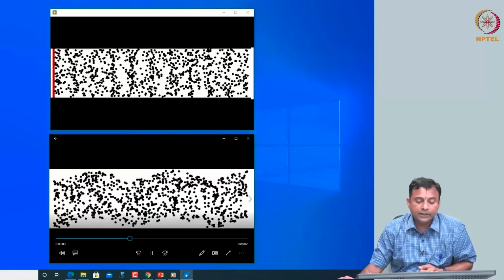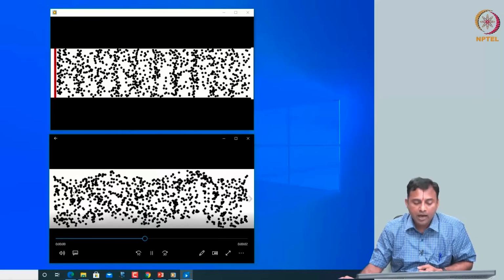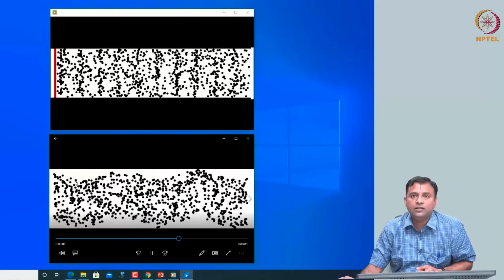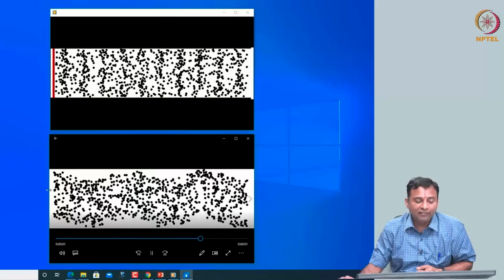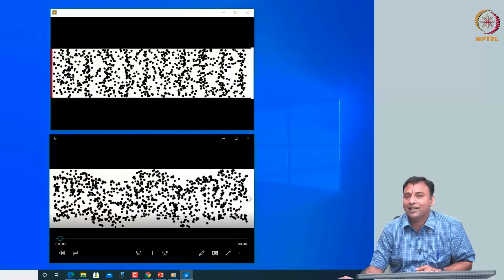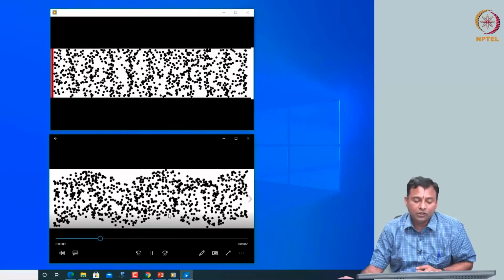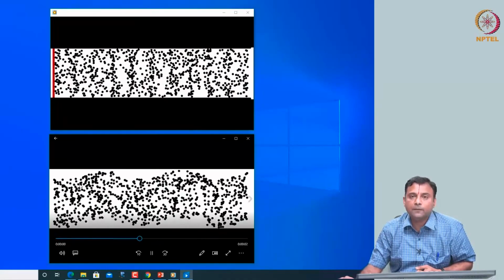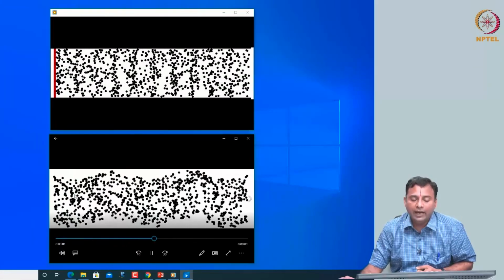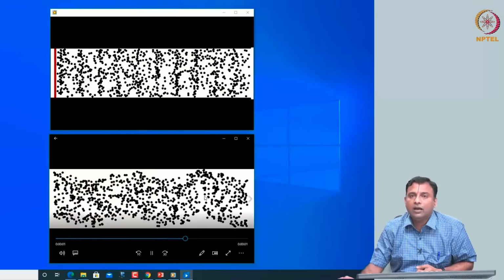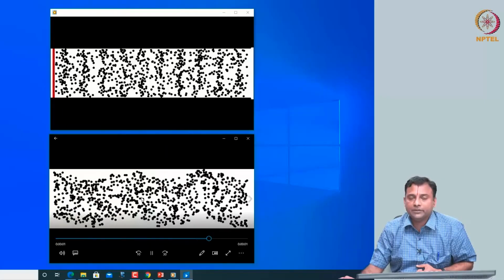So the particle is actually going up and down around its mean position, whereas the wave is going left to right, perpendicular to it. So this is a shear wave. The particle displacement, the particle motion, and your wave motion are in perpendicular directions.